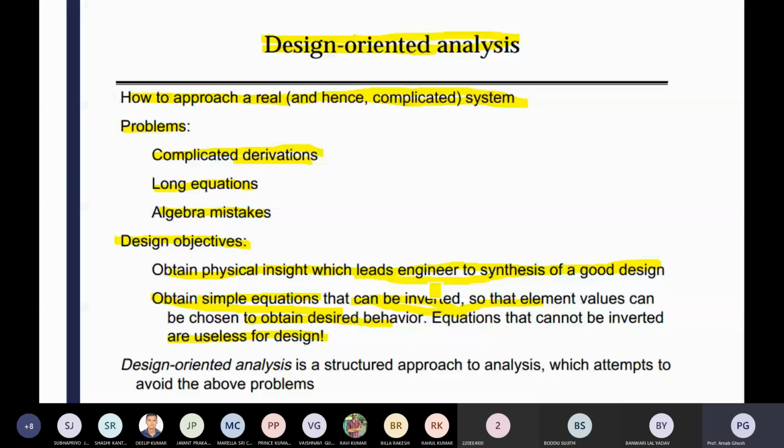If you reverse the transfer function of the boost converter, what happens? Poles will be shifted to zero locations and zeros will be shifted to pole locations. If you invert the transfer function of the boost or buck boost converter, the RHP zero, initially in the numerator, now comes in the denominator, meaning it is an RHP pole, a right half plane pole.